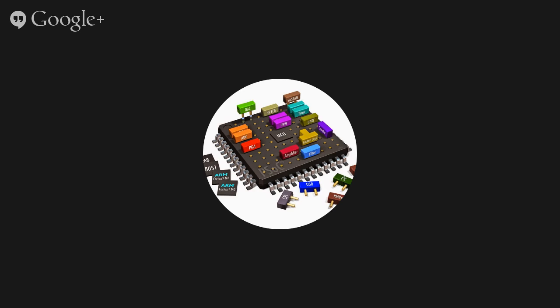Then I can come over here to main, and if I want to blink this LED, I need to write ones and zeros to this. I can say LED write 1, and then you put some delay in here, so I can say CyDelay. There are a number of utility functions that we provide for you within Creator, such as delay or power management, that kind of stuff. This takes milliseconds as a parameter.